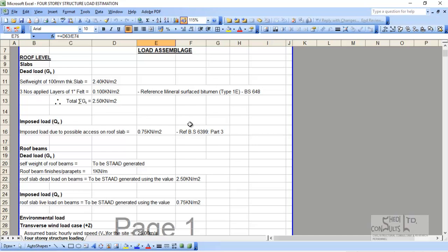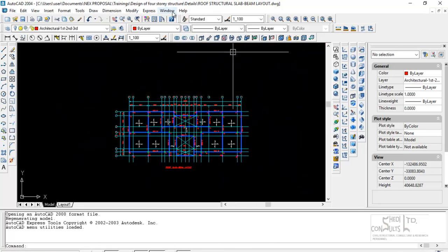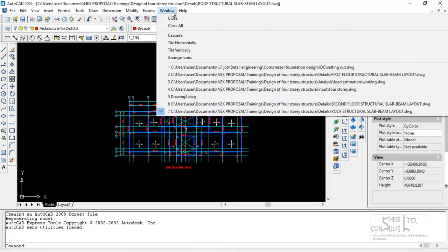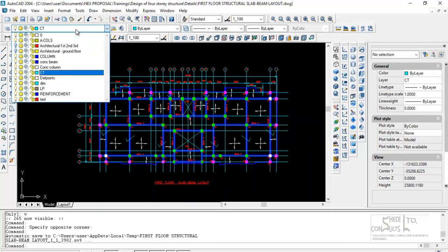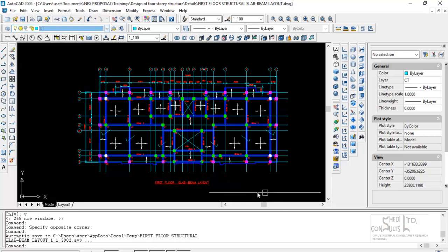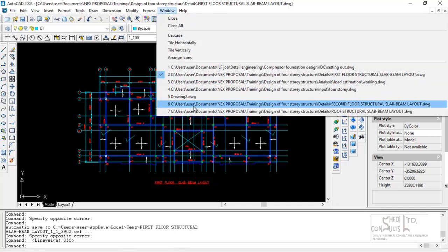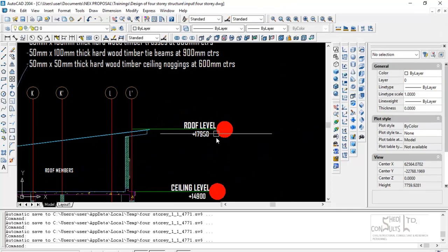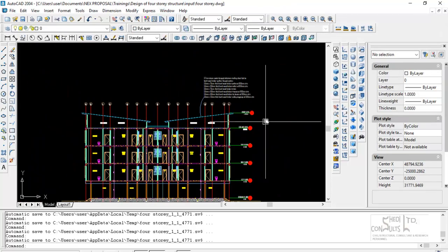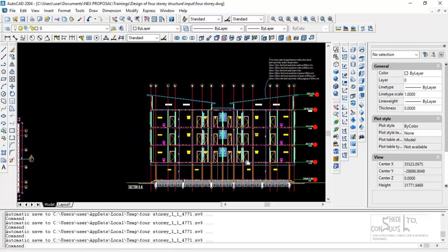What are the loads that the structure would carry? We need to look at this very, very carefully and intelligently. These are the very crucial aspects of structural design. The first thing you need to understand is the code of practice requirement for loading structures. Now, this structure is a 4-story structure, and its height from the architectural design is about 17.9 meters to the final roof level. So that's a structure that is going to be significantly affected by environmental loading.